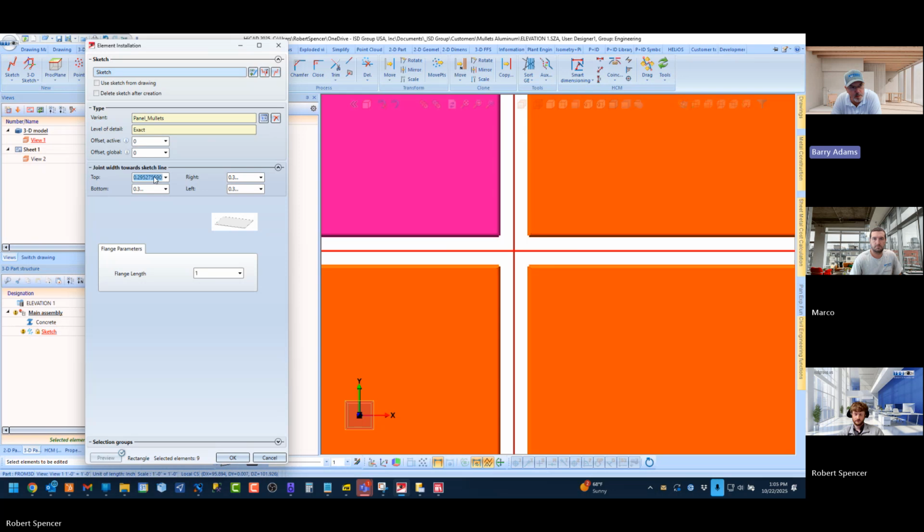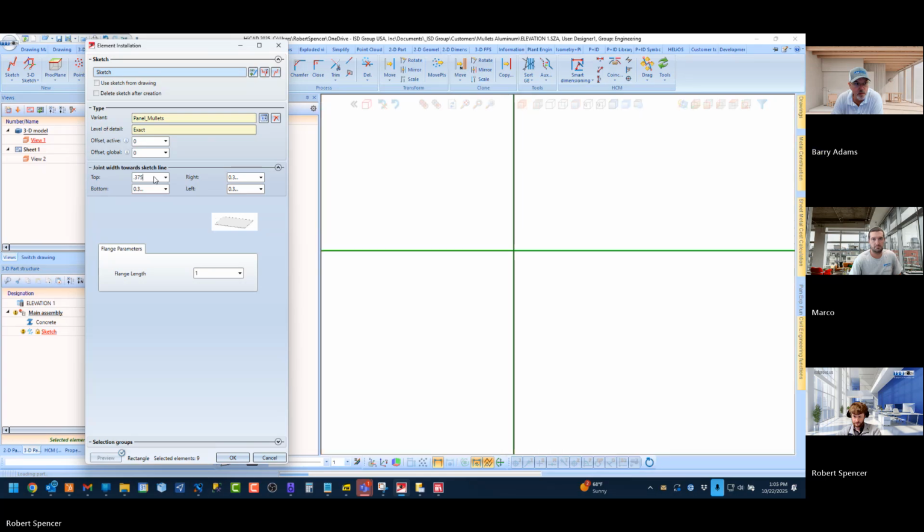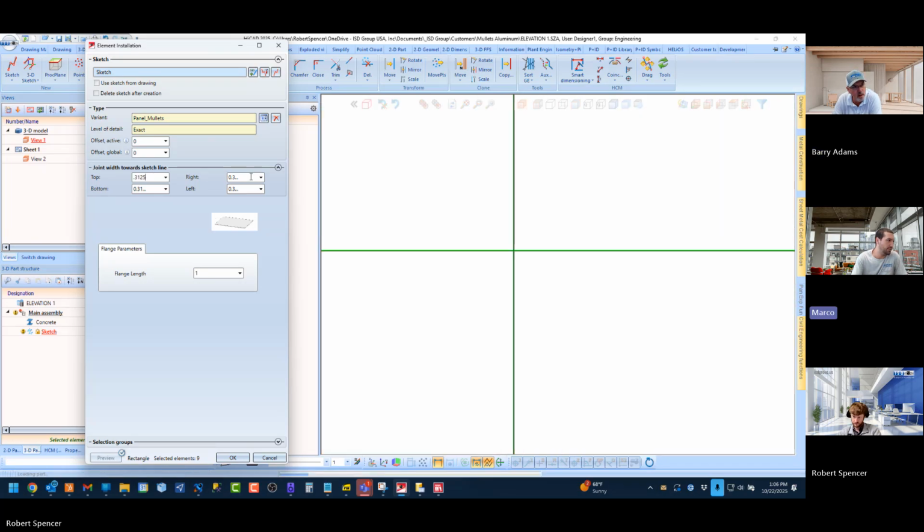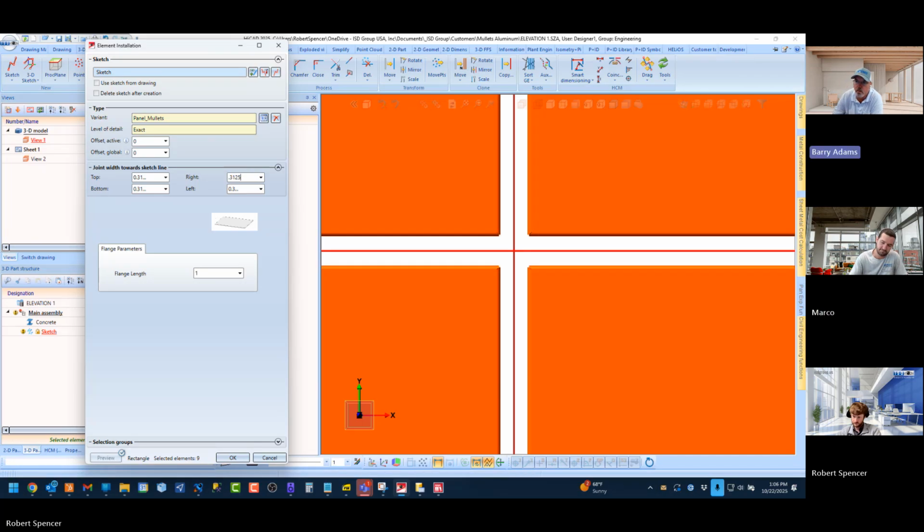So it'd be 5/8 divided by 2 if we like a 5/8 gap there. Well, 0.3125 would be, it's like 12 thou off. I think it's pretty close. Oh, 5/8? Yeah, 5/8 is what we shoot for. Yep, exactly. Got it. 0.3125 would be what we want on there.